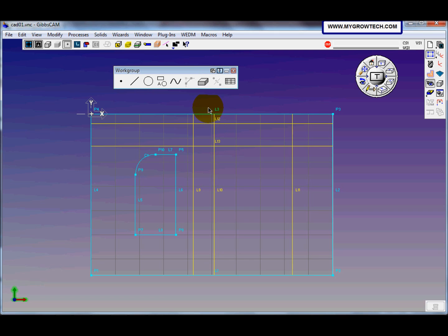Next, we're going to create a line by using the point angle. Let's click line again using the point angle. The point, it will be 63.5, the y will be 13.5, and the angle will be 30. And let's create a line.